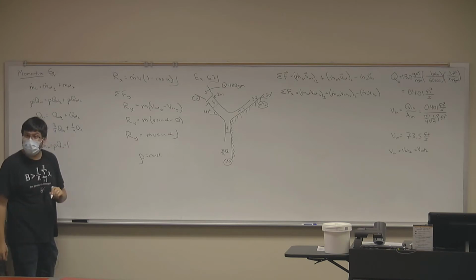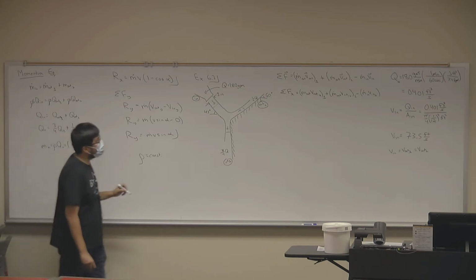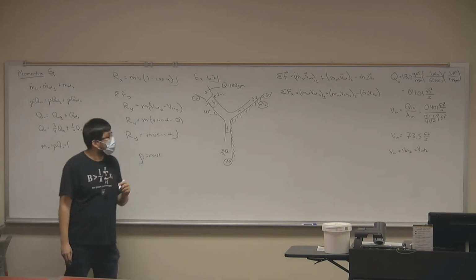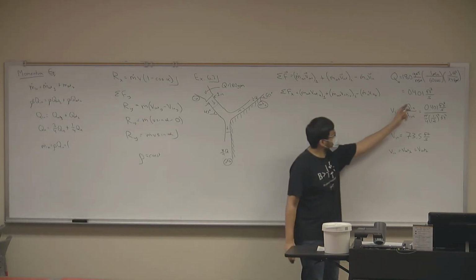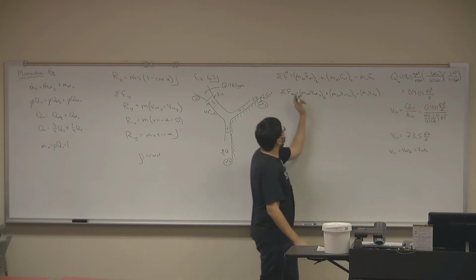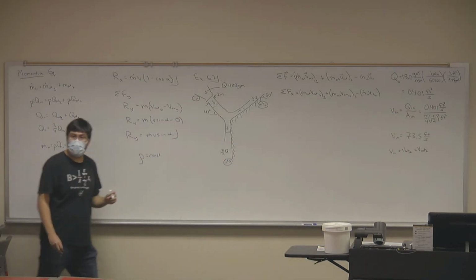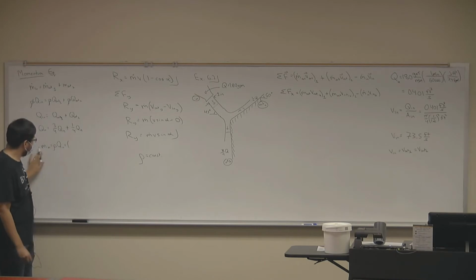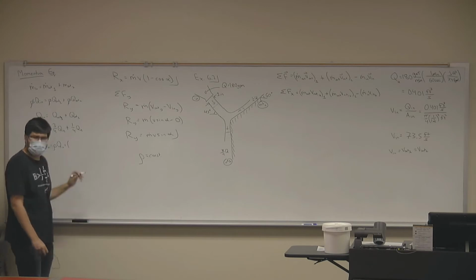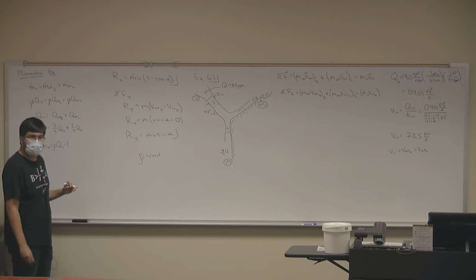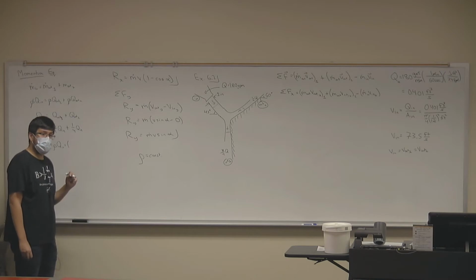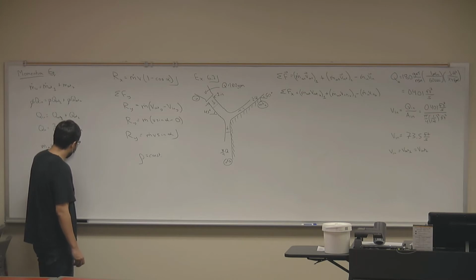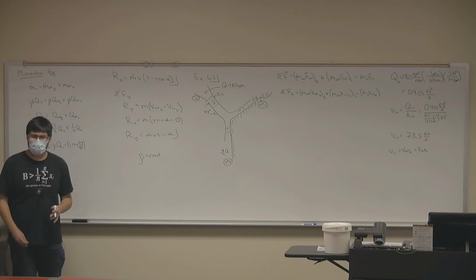Shouldn't it just be that number right there? Well, flow rate is 0.401, right? So what is mass flux in? Okay, I see what you're saying. So what's the density of water for English units? 62.4. The density of water is 1.94 slugs per cubic feet. If you forgot it, it's okay. Let's say you forgot. Who said 62.4?